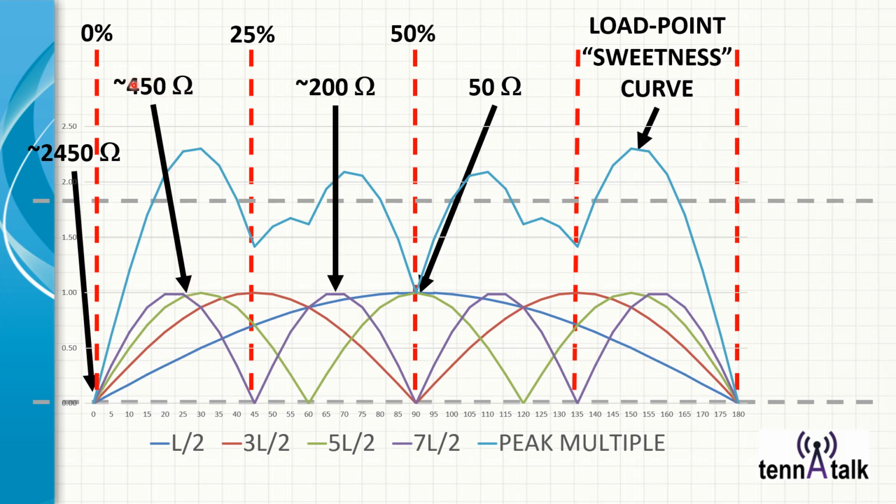Now, will that match to 50 ohms? No, you'll need something to match it up, and we'll get into that when we get into the getting efficient podcast. Now, the other antenna that we can use is an end-fed half wave.